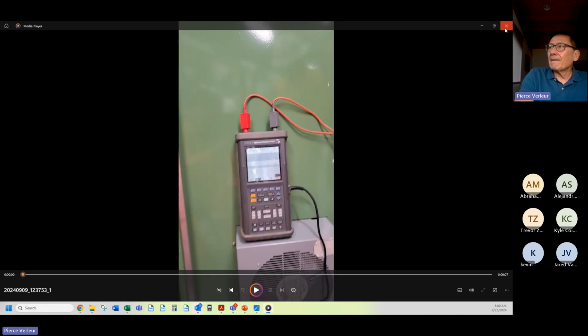Well, they used a fiber optic link. So these guys actually were pretty good engineers. They had the fiber optic link that covered the majority of the 600 to 900 meters. When I first heard it, I thought, propagation delay. Is this going to be out of phase? Is the motor going to be able to be commutated by the VFD? There was no propagation delay to speak of. The signal quality, as you saw, was pretty doggone good.